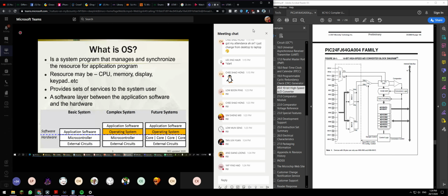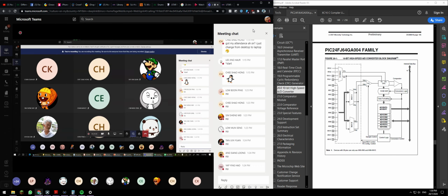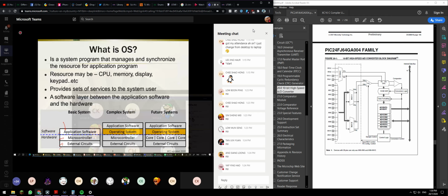You're just performing all this simple application software. This is what you always do, those days, and even until now, for my assignment 1, you are doing this very simple thing. What is it? Anyone ask questions? Why is it blinking? Then when the system becomes a bit more complex, complex meaning a lot of functions and a lot of tasks being called, that's why an operating system is needed on top of the microcontroller. The operating system will manage almost everything.